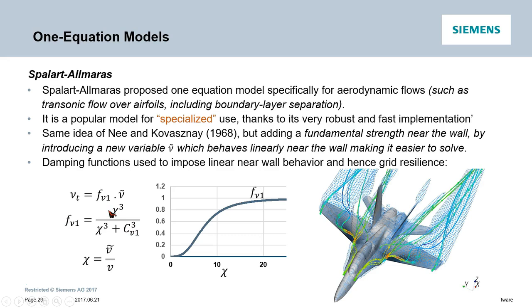And this model was designed and optimized for flow past wings and airfoils, and in some cases it performs even better than most advanced models for applications it's designed for. For example, 2D airfoil profiles and attached boundary layers. But as we move away from those nicely attached flows, it starts to struggle.